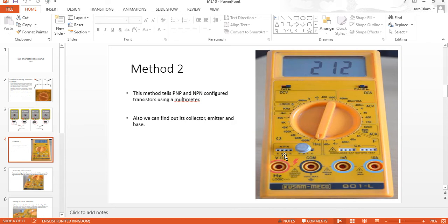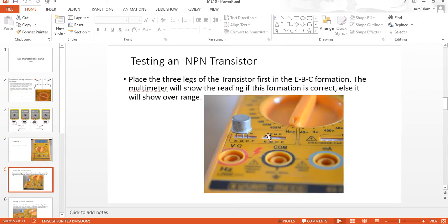But if you don't have internet, right, and you have to confirm it out, you can confirm it out with the help of a transistor multimeter, right? So when you set your transistor in HFE mode, आपने अपने ट्रांजिस्टर को कनेक्ट करना है by putting it in first emitter base collector of NPN, right? If it's showing a value in this scenario, it means all the three leads are connected to the correct point, which is the actual point, and your transistor is actually an NPN transistor with the emitter as first lead, base, and collector, right?